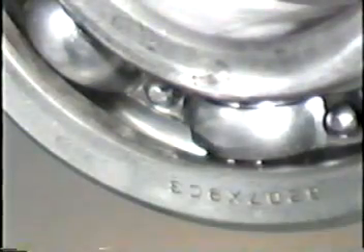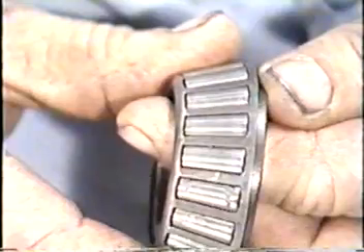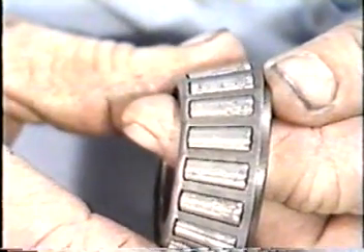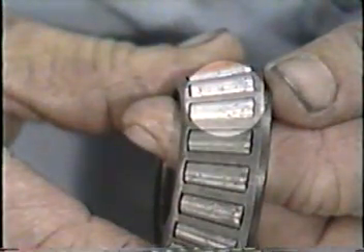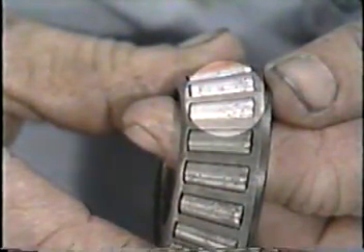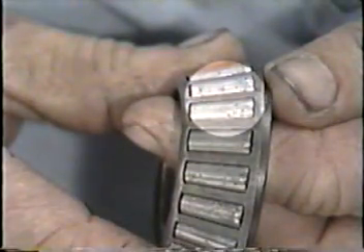Examine the bearing for cracks in the bearing cage or damage to the inner and outer races. Light particle indentation on the races is okay, but heavy indentations or any sign of spalling, where small bits of metal have actually been pulled off the surface of the race, are unacceptable.